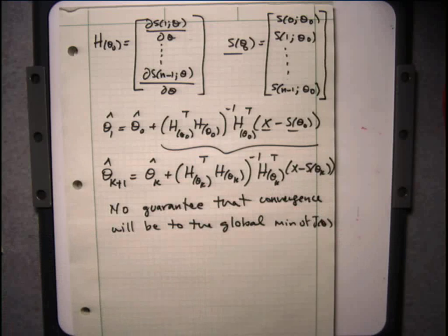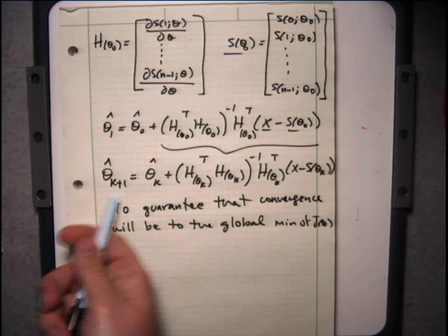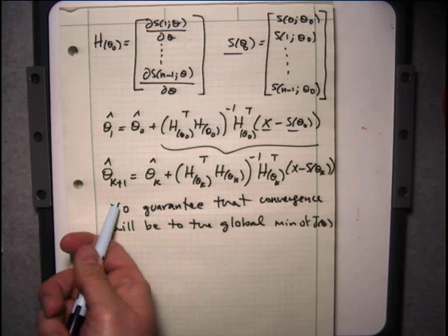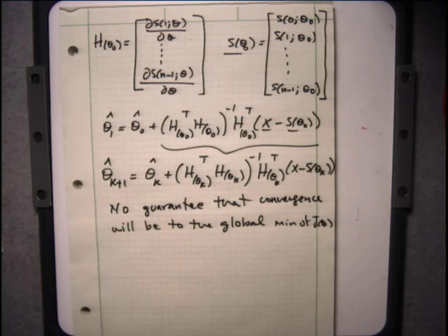Now if you want to update your theta for the next data point, you have to do everything that I showed you for the sequential least squares, including the linearization. So there are two iterations you're dealing with. One is the iteration to get the convergence here, and the other is an iteration which updates the estimate from theta hat n to theta hat n plus 1. That's why I'm using a different index here. This is what we call an inner iteration and an outer iteration.